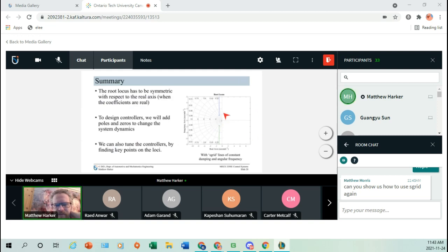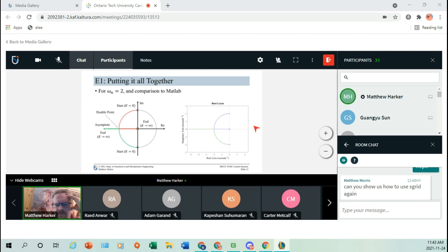Right, so basically what happens is if we take our second order system, we know it's parameterized by the damping ratio and the natural frequency, right? And as we found from that first example, by varying the damping ratio, the radius of this circle here is omega n. That is the natural frequency, depending only on the spring, not on the damping.